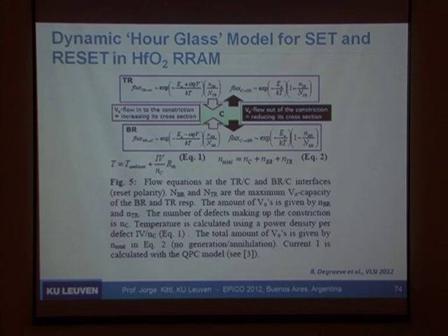The belief was that when you do the breakdown, you're putting a signature of how that filament is going to break and behave for the rest of its life. You can switch it or not switch it, but if you make a very strong breakdown, the filament will be wide, and the way it's switched will reflect that. If you make a better filament which is narrow, it will switch in different ways. So there's some imprint of the way you form the filament that will stay in the rest of its history. And that's, we were saying, the shape of this container or constriction in between.